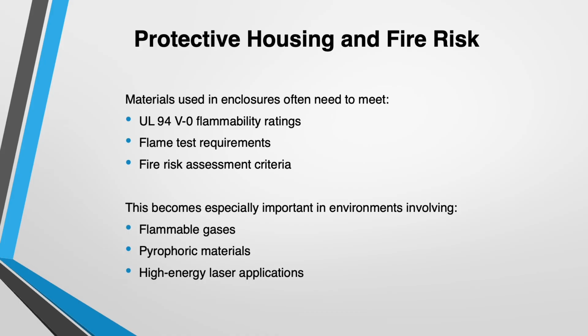Protective housing plays a major role in both radiation containment and fire prevention. Materials used in enclosures often need to meet UL 94V0 flammability ratings, flame test requirements, and fire risk assessment criteria. This becomes especially important in environments involving flammable gases, pyrophoric materials, and high-energy laser applications.